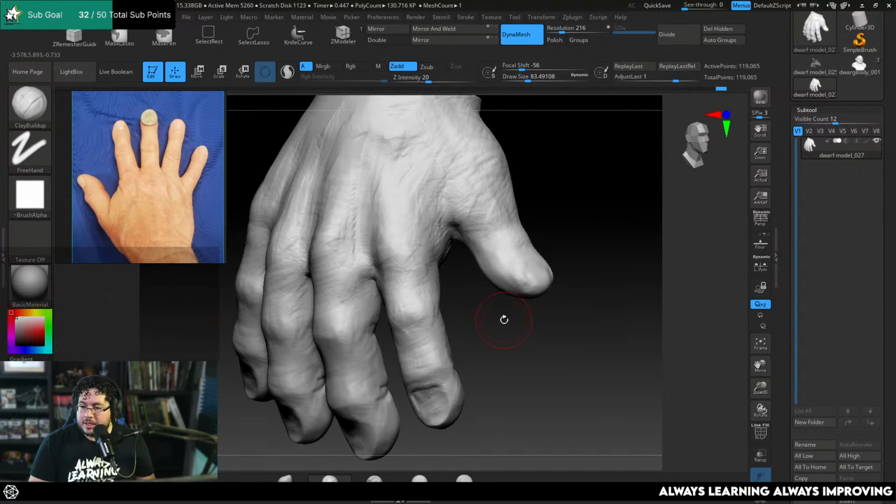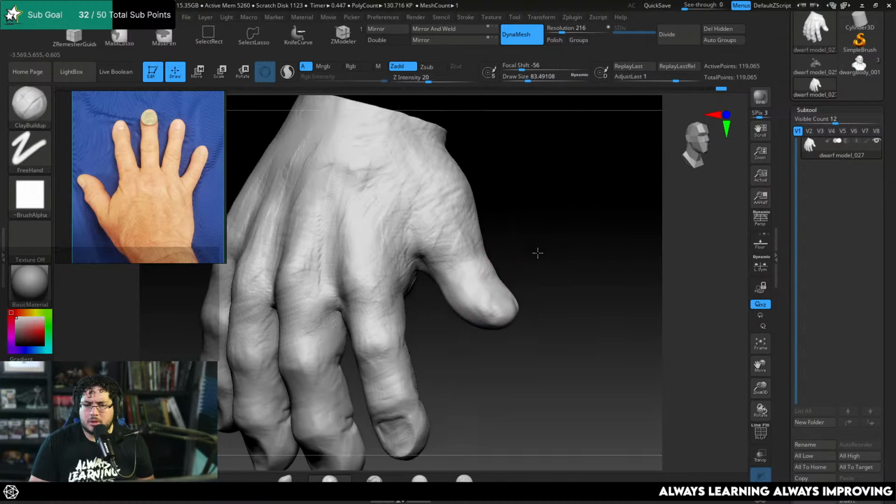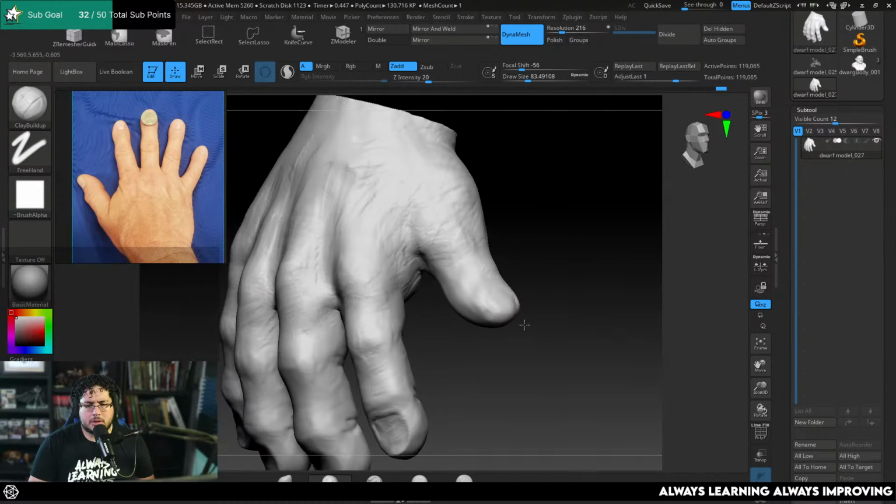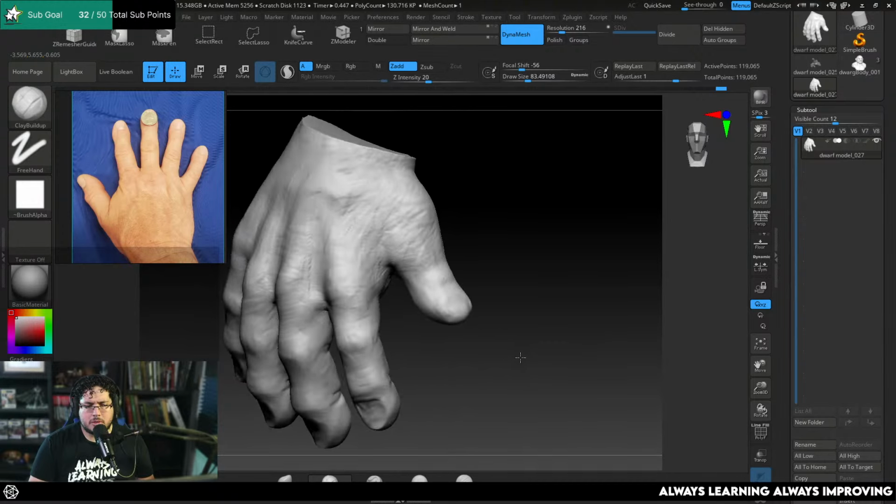I have exported my animation in Alembic when my UVs got vanished, so I transferred my UVs from my original one as I had the same number of vertices in the first one, but it didn't work. Where did you export the animation from? Usually when you export, the UVs should remain. There's no reason why you should lose them.